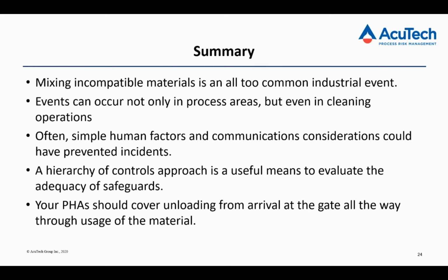Often, simple human factors and communications considerations can prevent these incidents, but a hierarchy of controls approach is even more useful in evaluating if you have enough safeguards for these sorts of events. And finally, think about when you do your PHAs, looking at these unloading operations really from soup to nuts, from the material arriving at your front gate to when it's finally put into your reactor or into your process.